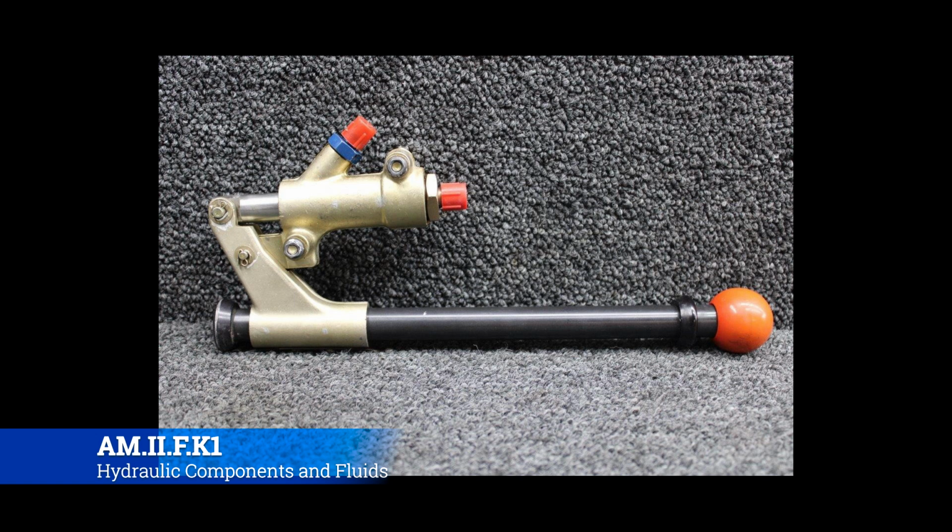And as you ratchet it up or down, it's going to push hydraulic fluid into the system under pressure. Whenever you come back down, there's a check valve to keep the hydraulic pressure from coming back with you. It's going to be locked into place, and then you're going to have a suction that pulls from the reservoir, and then you pressurize it again as it goes back up. The simple math of the cylinder that the hand pump is moving, and the aperture into which the fluid is being forced, will result in a certain amount of pressure.